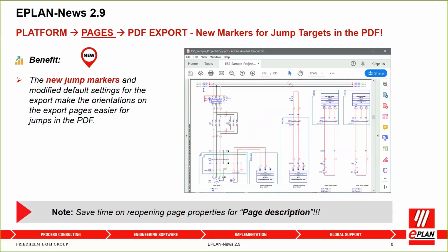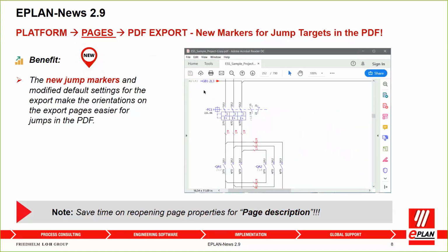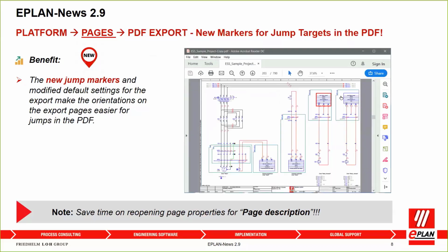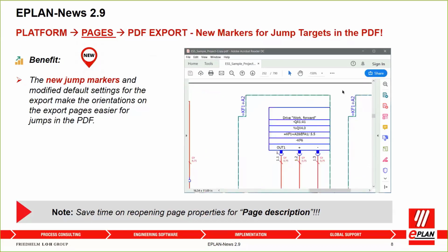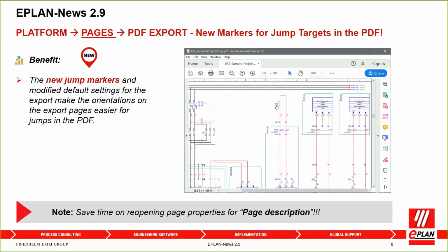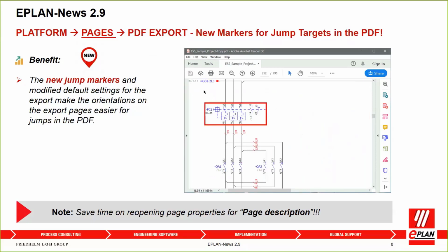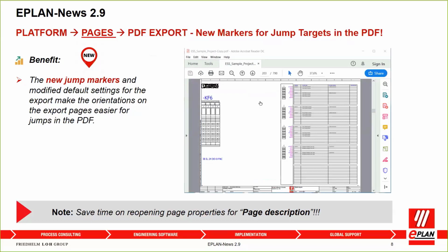As you can see, he opens the PDF, he's zooming in manually on the device that's flashing. Clicks the cross references, and this also works in forms, and as you can see, it's flashing red. This works for all cross references, contacts, PLC overviews, reports. The zoom feature can be enabled if required. Zoom is now disabled by default.